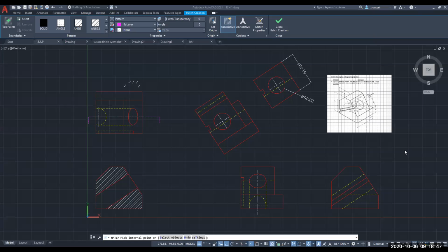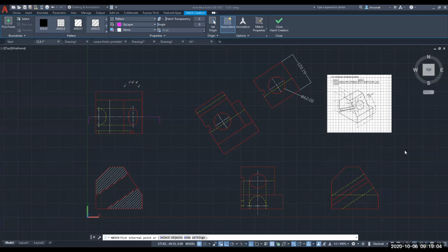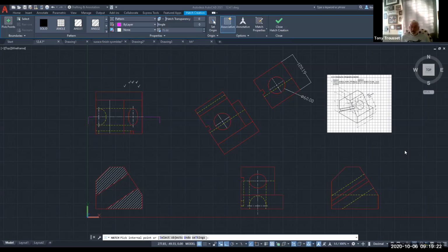And then there's also cool things like if you have a block and you place a hole on it, and you're planning to extrude it. Instead of doing a sketch first, you actually make an extruded sketch. So you'd extrude, and then you make a sketch in the extrude feature. So you make the feature first. You define the sketch, but you don't have to dimension anything. You put the circle on the block, and it automatically pops up with X, Y, and diameter. All you have to do is plug in numbers. You don't have to add any dimensions.